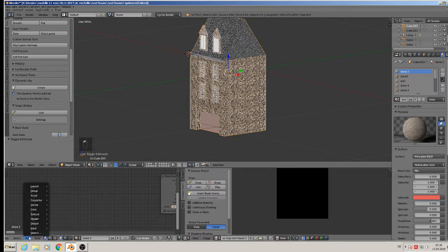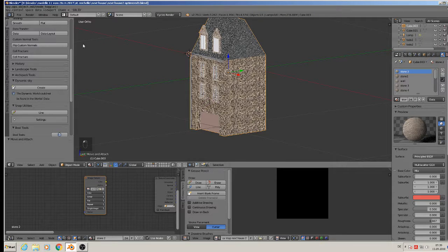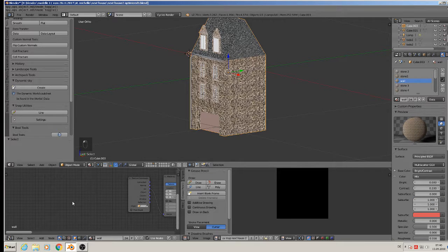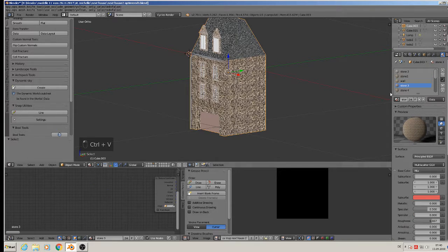So that means add texture, image texture, and the UV map there. That you must open, and it must be highlighted, so it must be yellow and clicked on. Then Control C to copy, and we go to each material, Control V, plug it in, click on. It's important that it is selected. That is the mark for him, that he should select this material and bake it. When it is not highlighted, he doesn't bake that.